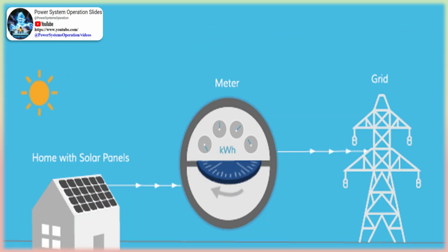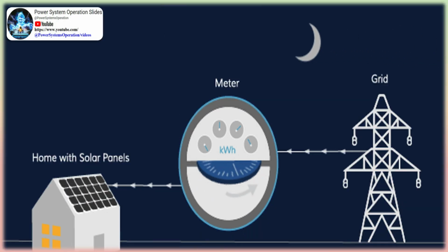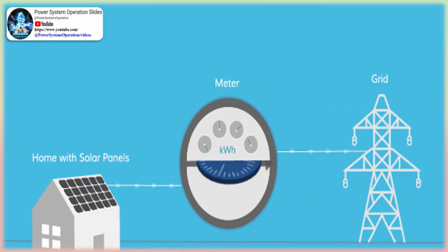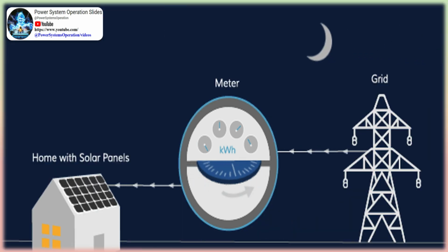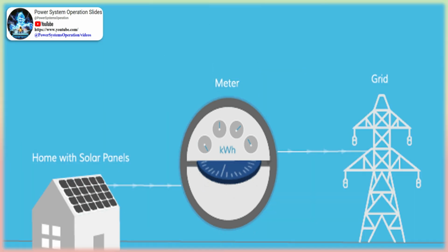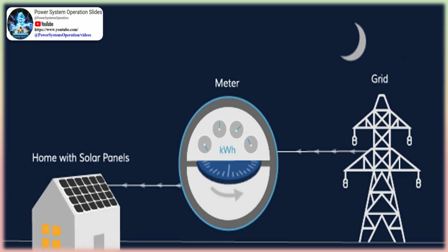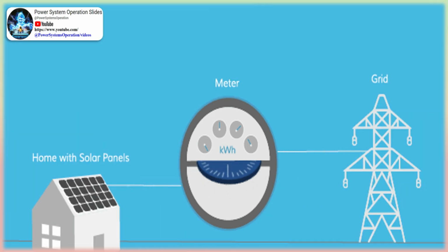The basic issue in solar generation is that the generation is intermittent, so the end user might face problems in the nighttime if the solar rooftop is standalone type. The problem can be solved by installing solar rooftop with a battery: in daytime, the user uses the solar generation and in the nighttime, the user uses the power from the battery. However, rooftop solar with a battery becomes too costly.